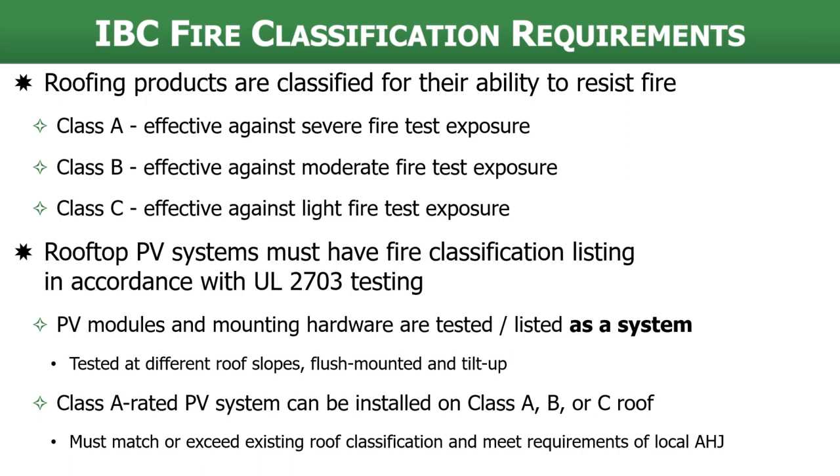The reason this fire classification came around was so, hey, we don't want the racking manufacturer to have to list and test their product with every single module manufacturer out there. What happened was if a module was classified as a certain type, then the rack could get tested and listed with that type of module as a system. We're going to get into module type here in a second.